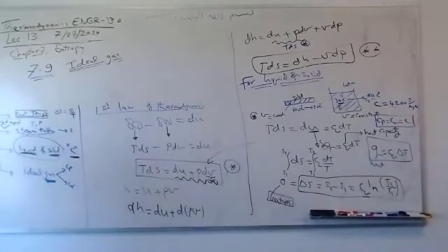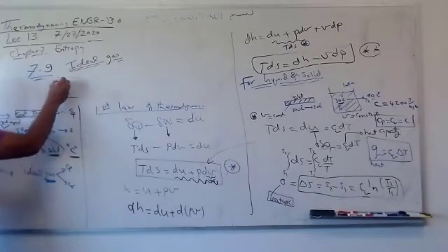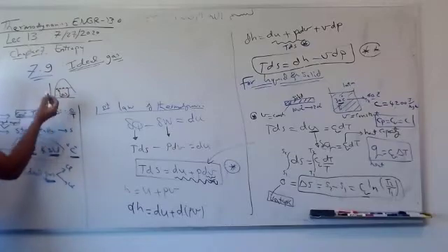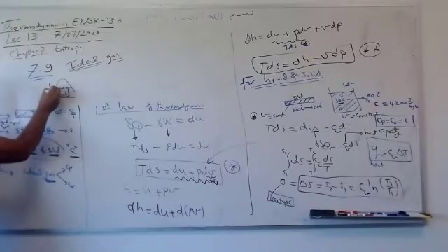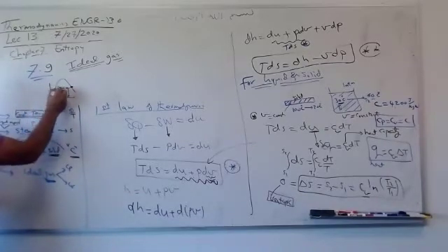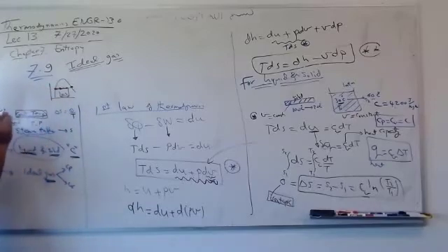There is no heat addition. But actually for steam table, you may have the temperature the same. For example, if you are working in this saturated mixture, temperature is the same, but you have huge delta S. Why? Because you have phase change. You're going from pure liquid to pure vapor, or some more vapor. So when you go this way, you have phase change.